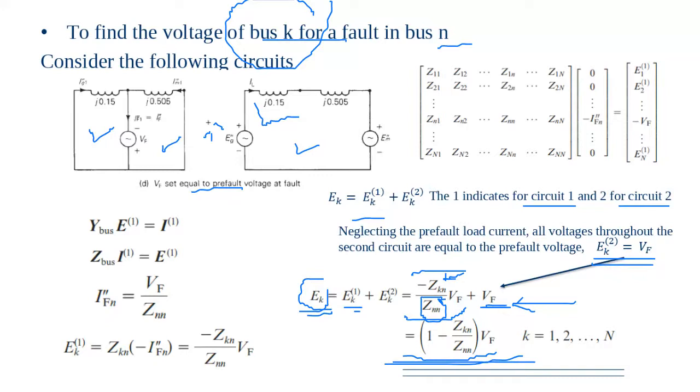And this is also the voltage at the bus before the fault. The fault happens when the voltage at a certain bus was, for example, 0.95 per unit. It was at this voltage, then we calculate the fault current. Of course, we are doing this at the sub-transient. But at the end, at the faulted bus, the voltage will be zero because it touches the ground.